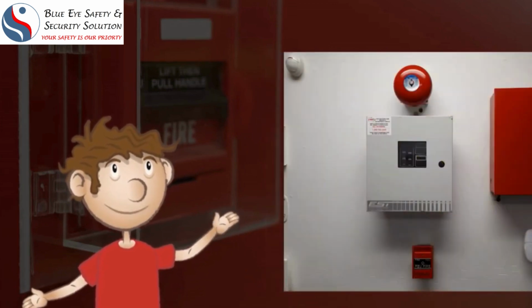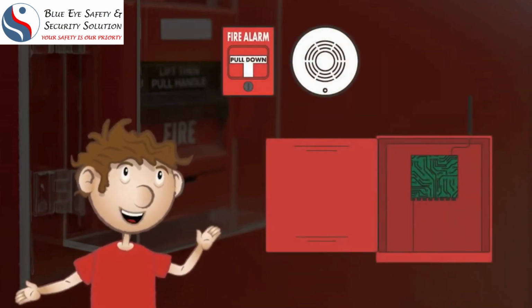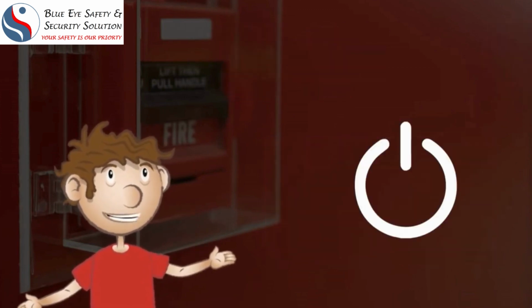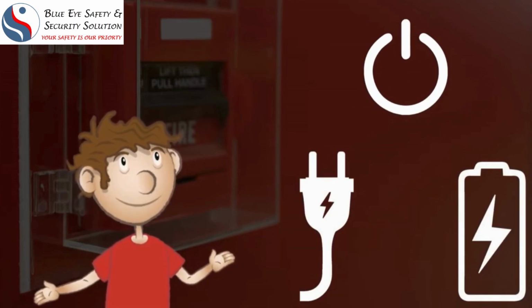First is the control panel. This is the brain of the system and is the central hub that monitors inputs. The control panel also controls output actions and sends information to notification devices. Second is the power supply. When it comes to powering your fire alarm system, both a primary and a backup power source are required.